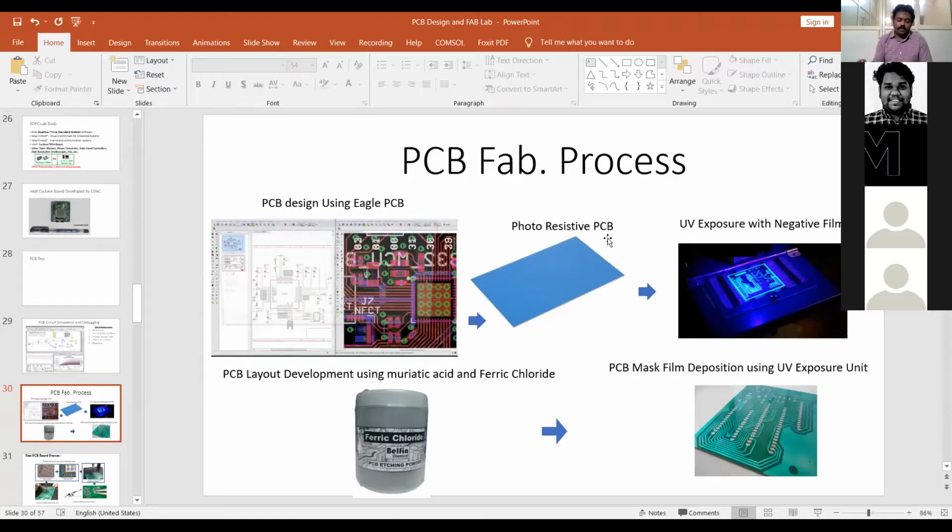PCBs are possible in industry, where you can go for industry-level establishment with 10, 20, 24-layer PCBs, even 32-layer PCBs. That is very common for RF circuits, especially for space applications and radar applications. So for 5G communications, the security you want, the efficiency you want, and the lower electromagnetic interference you want, you have to go for a high number of layer PCBs.